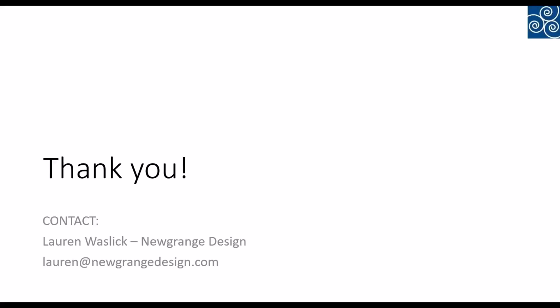Got it. And then maybe we have time for two more. One is, can you add a stiffener, or I would assume any of the other flex-unique stackup materials, can they be accounted for when you're running simulations? Maybe this is one for you, Matthew. Yeah, so if you're using one of the Sigrity tools, you can definitely account for the stiffeners and those materials in your stackup, and they will be considered when you run extraction, so yes.